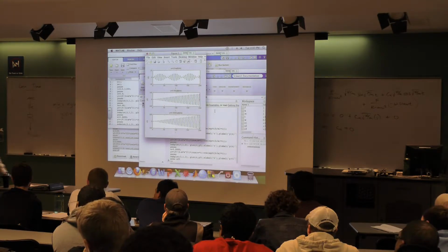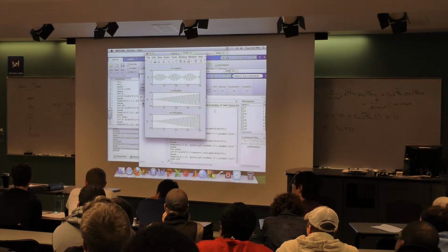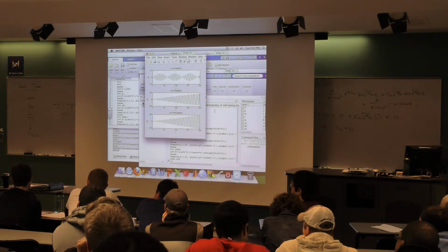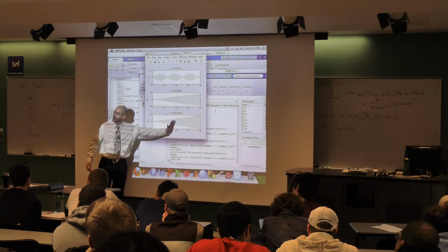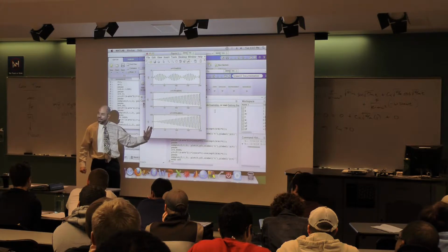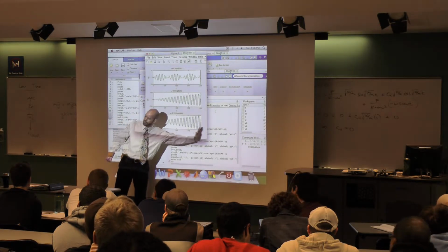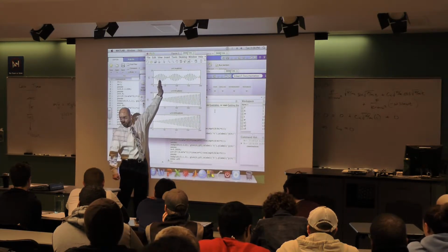So in engineering design, if I'm designing an aircraft engine that's got a bunch of disks that all spin just like your tire spins, I'm going to hit natural frequencies of the wing, of the rest of the engine, of the overall aircraft. And the key thing is, just because I hit that frequency doesn't mean it's going to break. What it means is, I better not sit there, right? It takes time for the amplitude to build. Even this, it takes time for this to build.